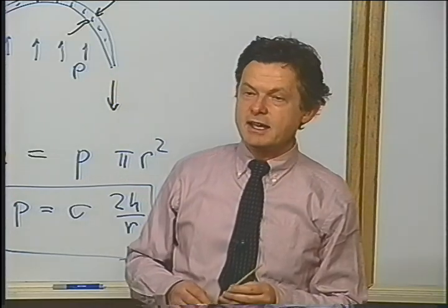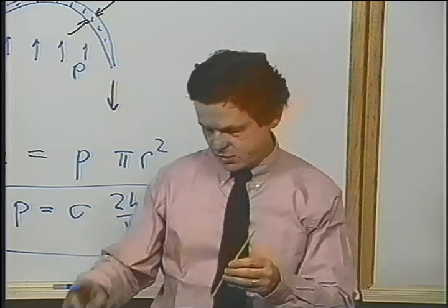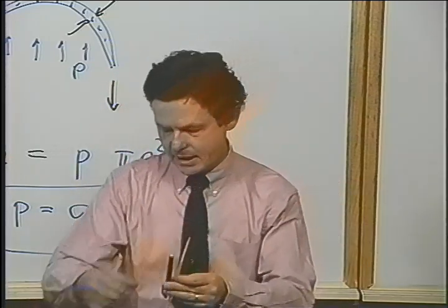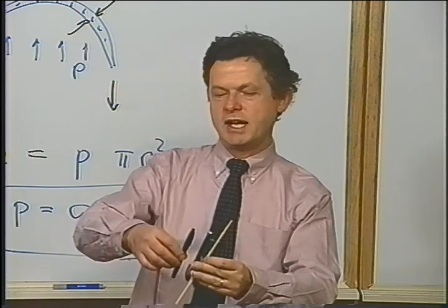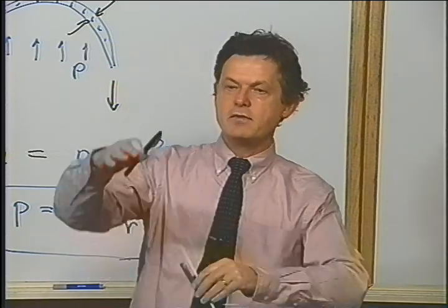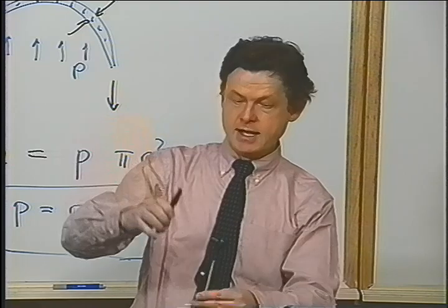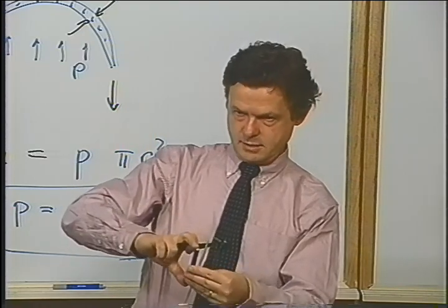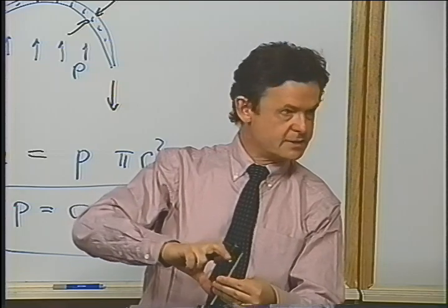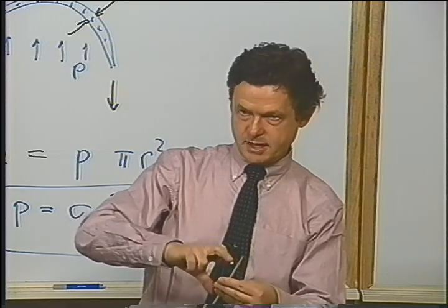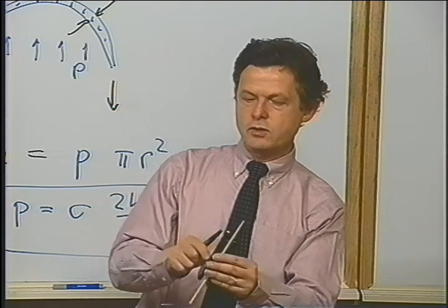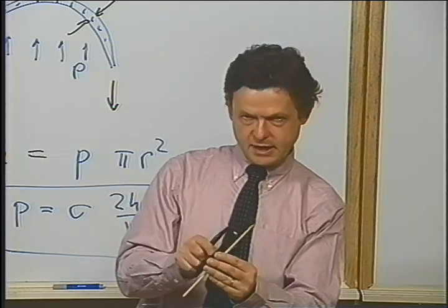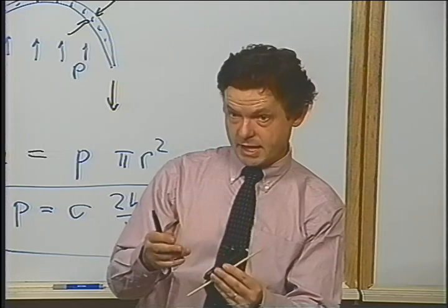Certainly, if you have a fiber-filled system, you have, say, large objects in a continuous matrix. Now, if your flow channel is much larger than the size of your filler particles, then the continuum assumption is okay. If you want to describe the flow in the vicinity of these fibers, you have to renormalize your approach.